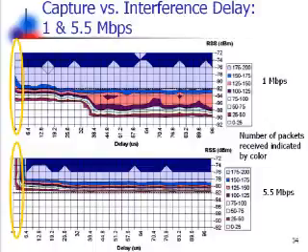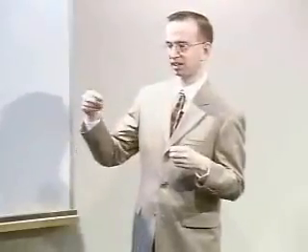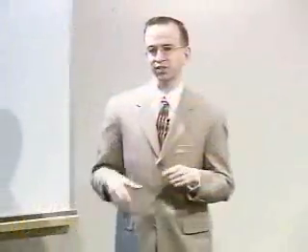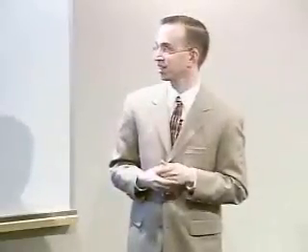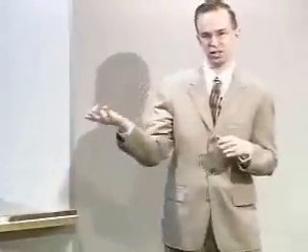Okay, so there's just a couple points I'd like to make here. First of all, if there is precise synchronization, and the interference is allowed to occur at the start of the packet, that's when behavior is the worst, because the receiver doesn't even have a chance to start acquiring that desired transmission at all. And then for the 1 megabit per second case, after about 32 microseconds, we see an additional benefit where it's locked on to the signal, and it can, in fact, receive packets that are weaker than the interfering signal. This is because of the robust nature of the modulation.